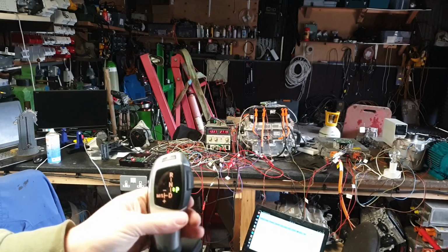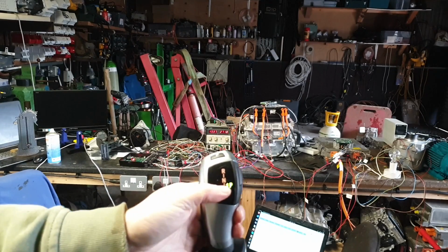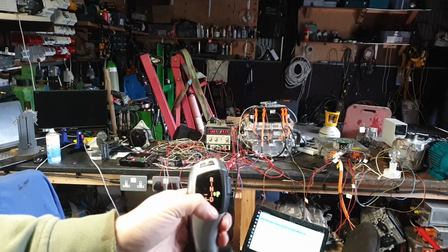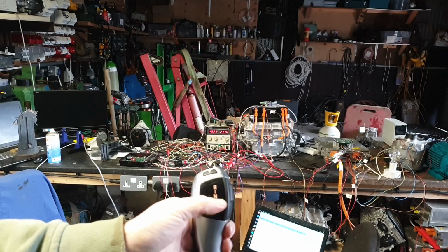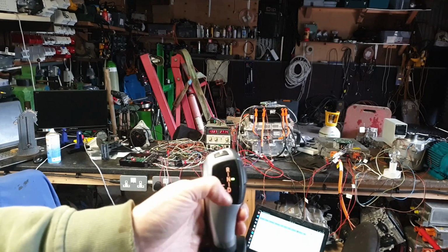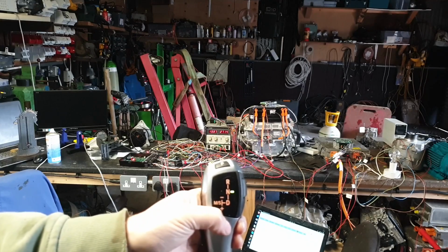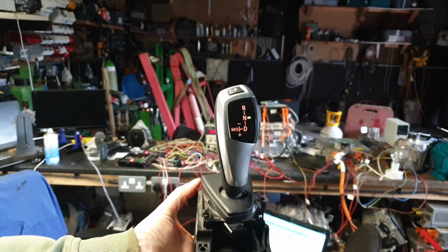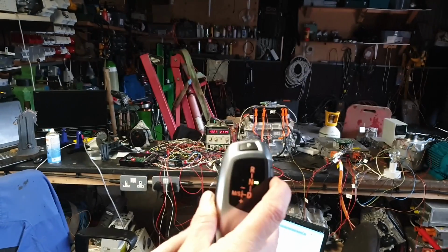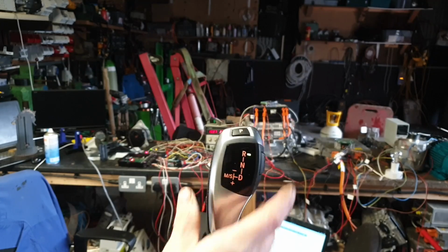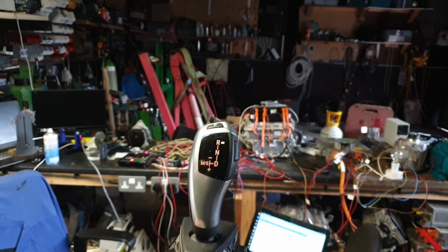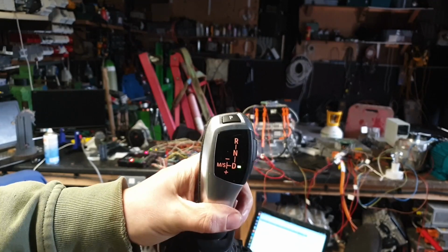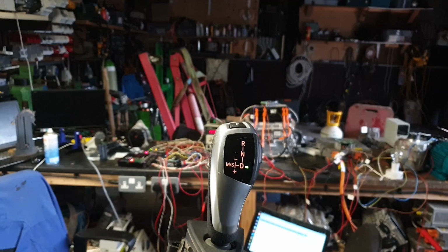And currently on its display here, it'll show the current selection that the VCU is in. So it's currently in park. If we press the park button, we go into neutral, and we can then, just like in an F30 or other car that uses this, press the unlock button and then double click forward to go into reverse. Then you can double click back to go into neutral and double click back to go into drive.